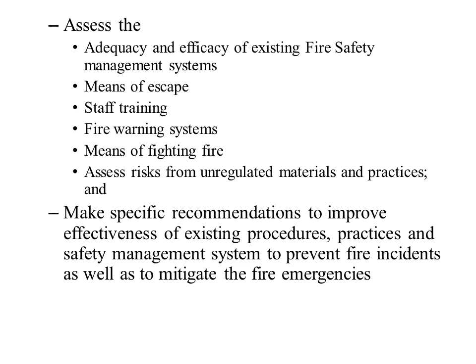Next, remove the cylinder to a safe and ventilated space. Do not bring any flame or fire near the cylinder. So these are the steps that have to be followed whenever there is a leakage.